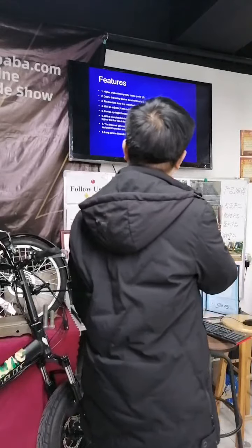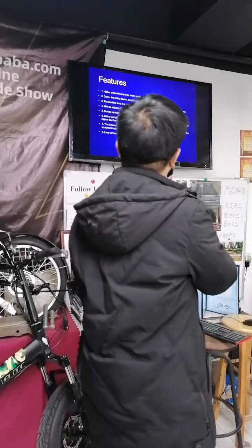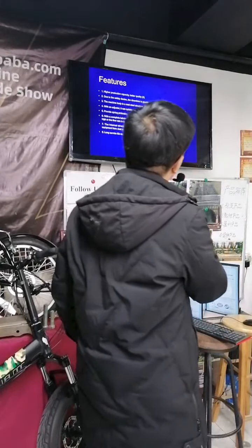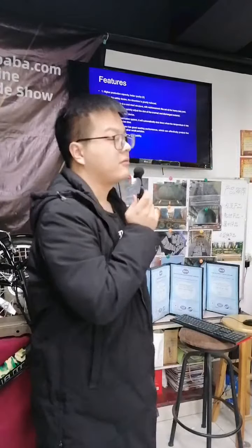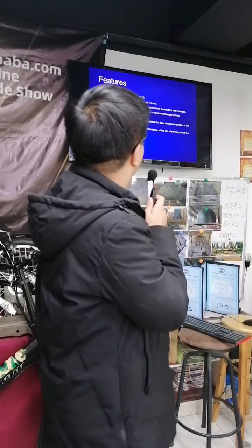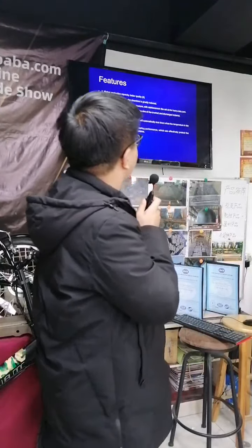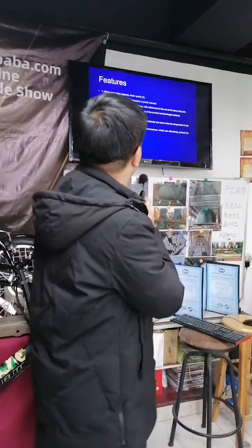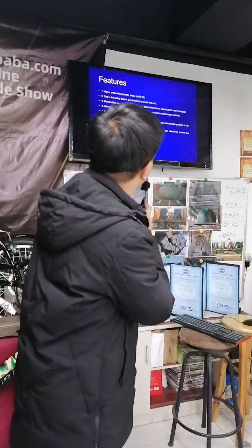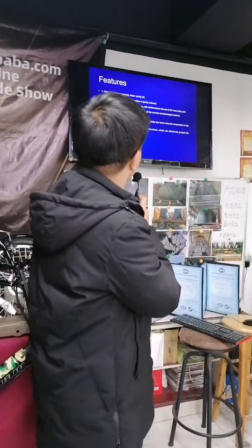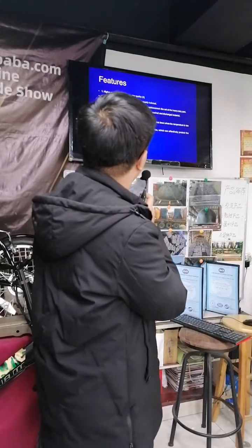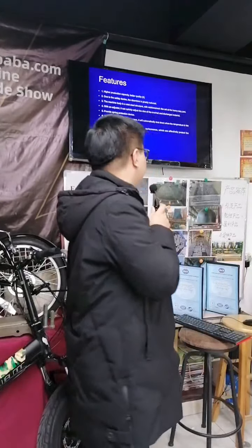3. The machine body is a cast steel structure with reinforcement ribs. 4. The heavy duty part is an adjuster. It can quickly adjust the size of crushed then discharged material. 5. Provide spring protection device. 6. It is a complete system. It will shut down when the temperature is too high or flow rate is too low.